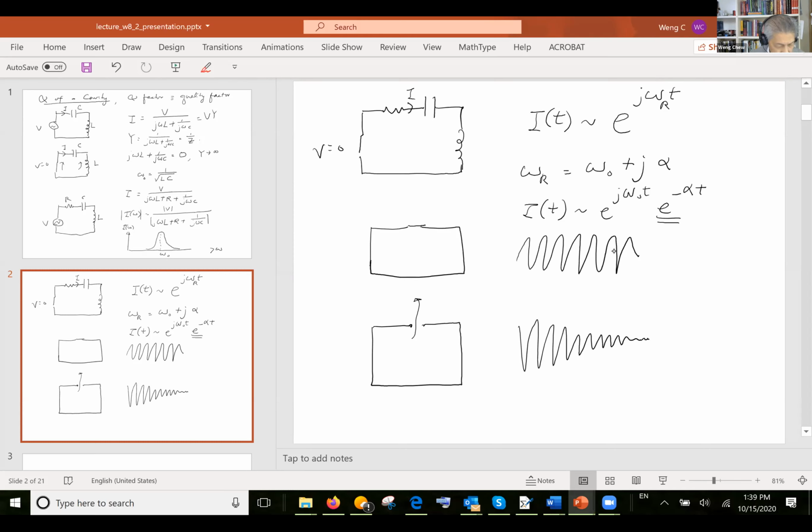So in general, what you can say is that when you have a cavity loss, the electromagnetic field inside the cavity would be proportional to something like e to the minus alpha t plus a sinusoidal component. If you convert this to phasor, and if you put a R naught there, then the phasor would be something like this, okay? And the magnetic field will also be behaving something like this.